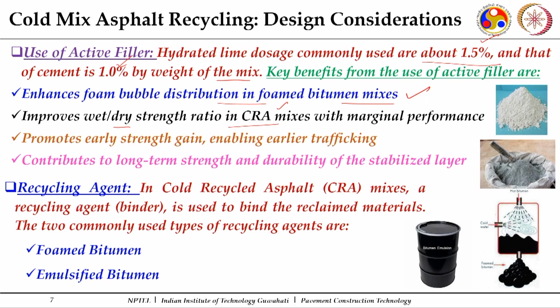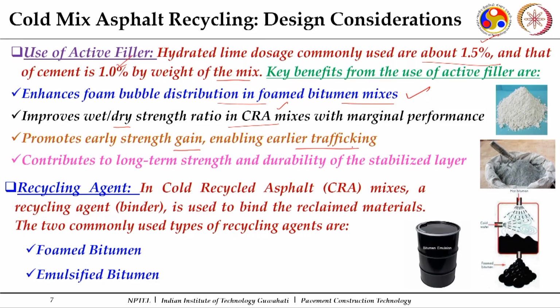This is quite useful if these mixes are showing marginal performance without these additives. It promotes early strength gain, because as we have seen, the curing periods may range from 3 days to 7 days. So early gain in strength is required so that it can be opened to traffic. Hydrated lime and cement, as active fillers, play an important role. They contribute to long-term strength and durability of the stabilized material. That's why these are quite popular in the design of cold asphalt recycled mixes.